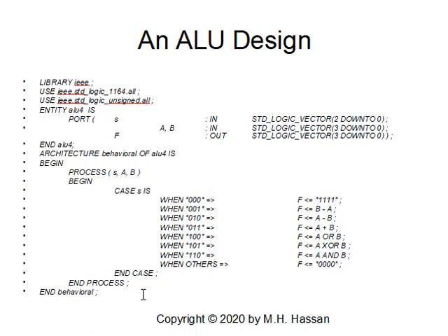This is a simple ALU, but we can have a very complicated ALU. The inputs to the ALU, we have the numbers A and B. And here it's a 4-bit ALU, so A and B are 4-bit, defined as standard logic vector, 3 down to 0. The select signal S is 3-bit because the ALU has 8 functions, 2 down to 0. And I have F out. F is a 4-bit function, has to be because it's 4-bit technology, and F will be out in standard logic vector 3 down to 0. I will end ALU4.